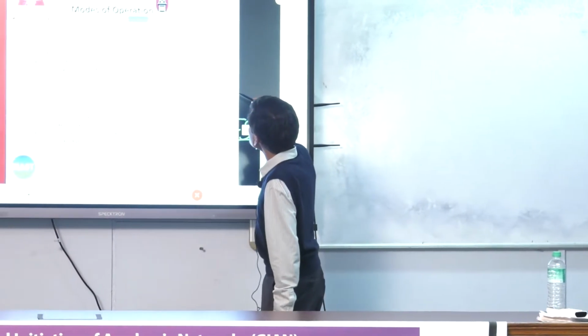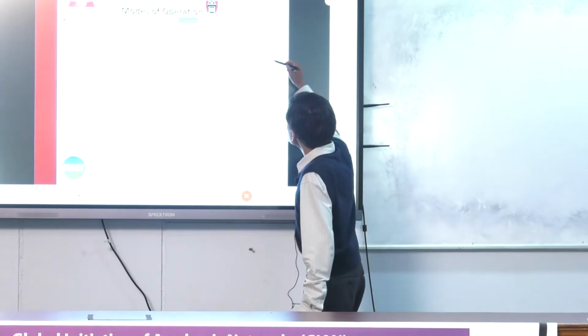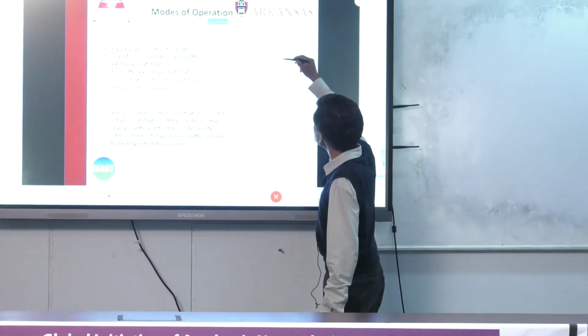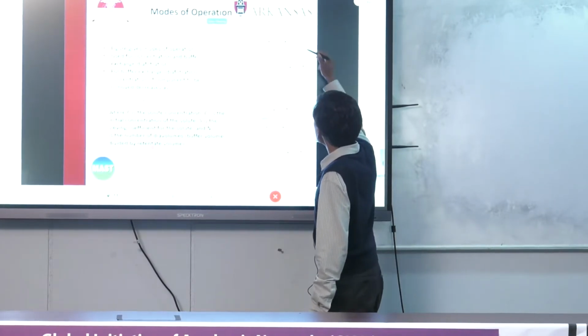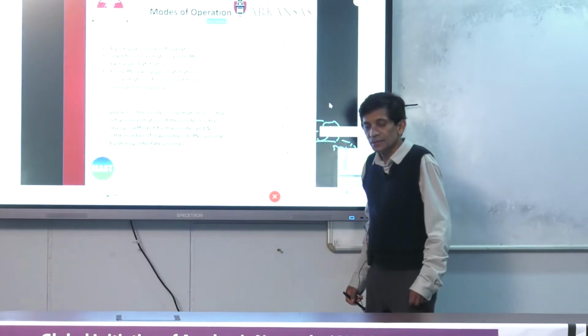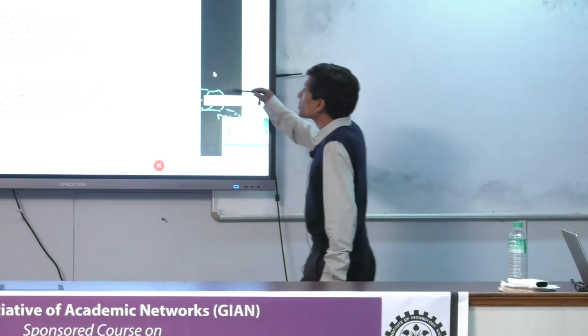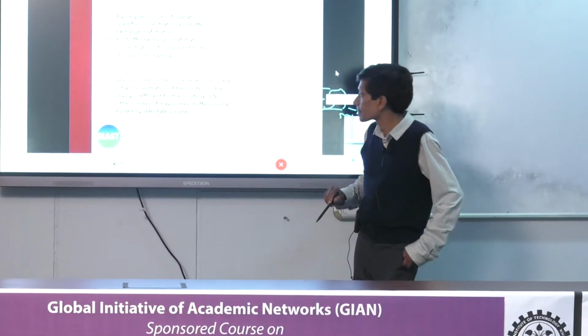We can also run this in the following mode, where here's our recycle tank. So it's the same as this one, except we have fresh feed coming in here. So we are recycling the feed, plus we're bringing in fresh feed, and then we're removing the filtrate. Okay? So that's a very similar way of operating. It's just a little different in that all of the feed is not in the recycle tank. We're bringing it in stages.